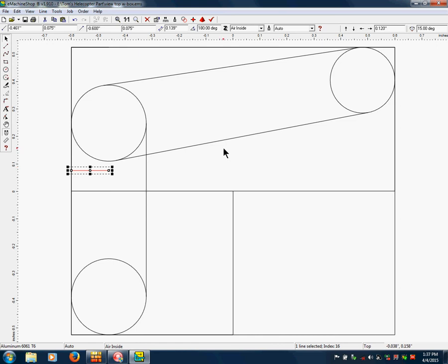Now that top measurement where I've got on all three of these, that I'm going to change because I may not have to, but I need to make the stock larger to start with than the actual part, so I don't have any flat spots or scalps or anything in it. So I'll probably play with that top dimension to start it higher. It's mainly the depth that I'm looking at, but I don't want it immediately coming into the material before it starts the actual operation.